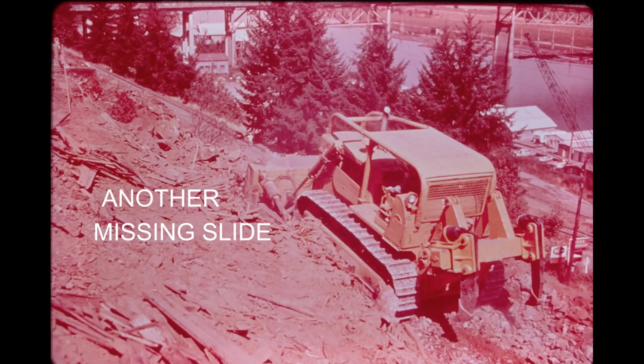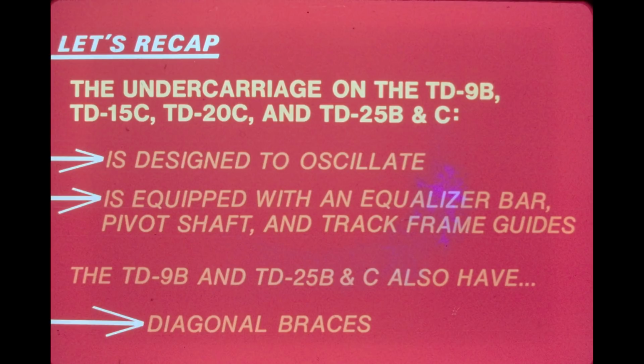Let's briefly review our discussion about dozer undercarriage mounting. The undercarriage on the TD9B, TD15C, TD20C, and the 25B and C are designed to oscillate. All are equipped with an equalizer bar, pivot shaft, and track frame guides. The 9B and the 25B and C also incorporate diagonal braces.